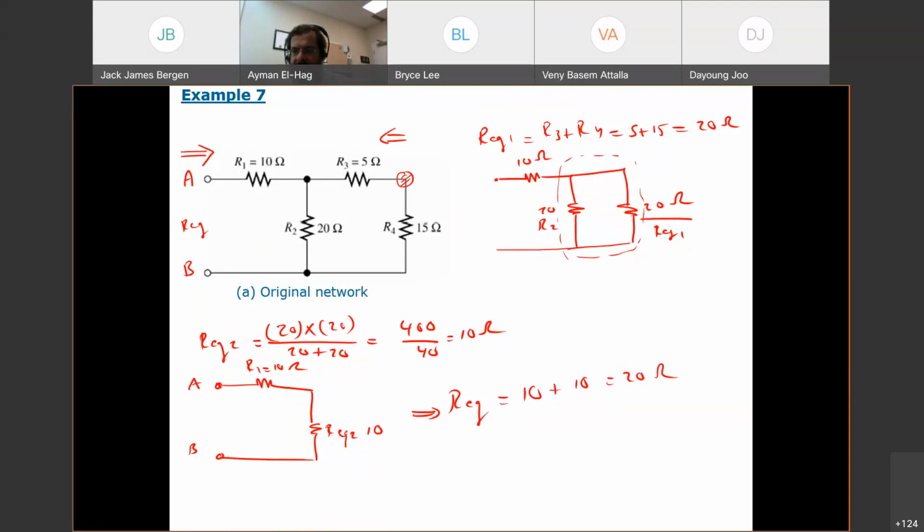I don't fully understand the question, but if you mean why we go from this side, not from that side, it is because on this side you can easily identify the resistors connected in series and parallel. On the other side, these two points are floating. They are not connected to anything. So it will be very, very hard to identify anything in series or in parallel between these two points.